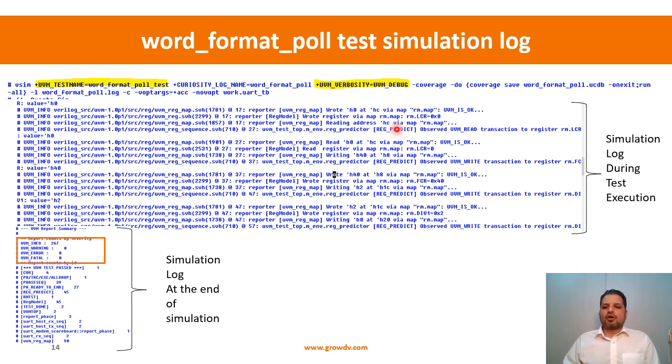So there are various things for which we want standardized formatting. That is very hard, because one component owner might choose one style, another component owner might choose another style, and we don't have any control. But when we do it in UVM, you have the control, and this is a very important part, because then anybody can look at the simulation log, understand it, and extract and process the information. So that is the second part. You looked at first the configuration information, and the second part is that the test has run and the messages from different components have been logged in a standard format.